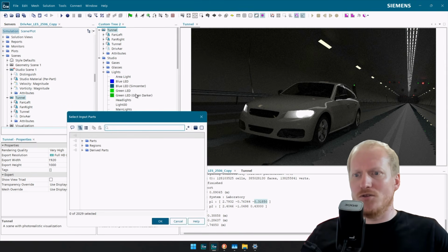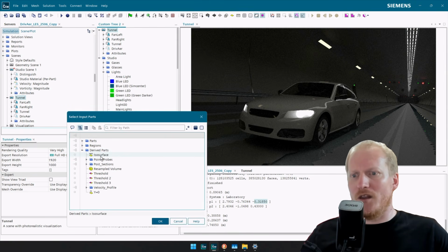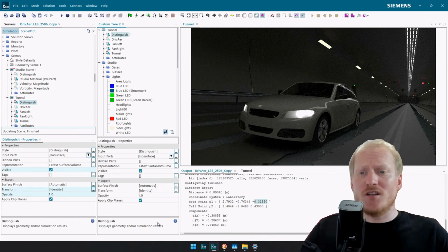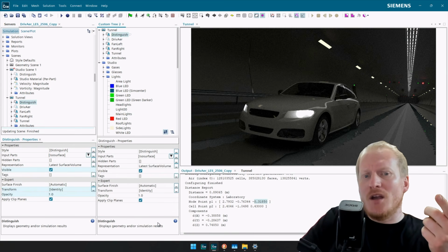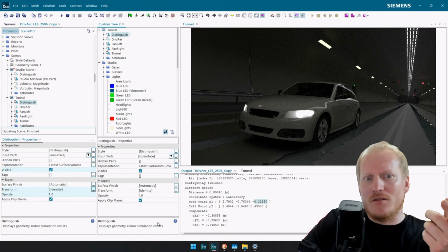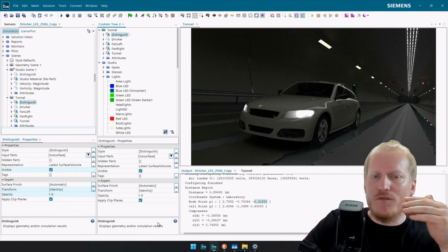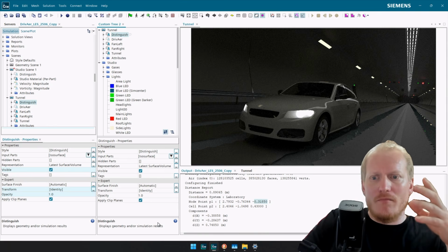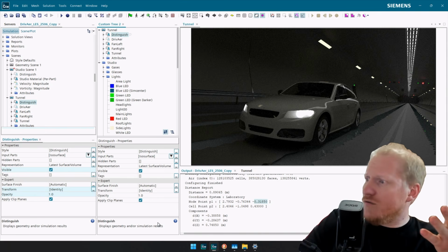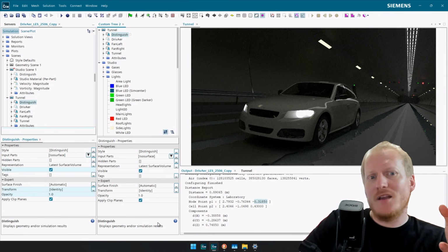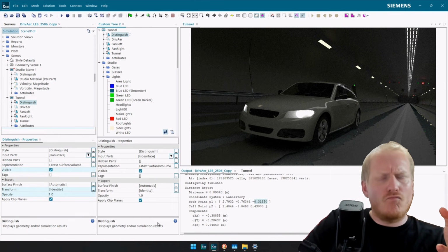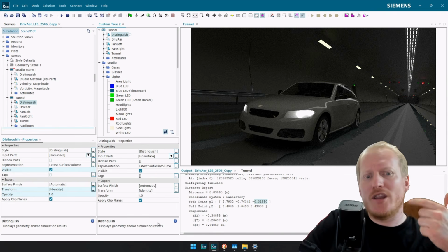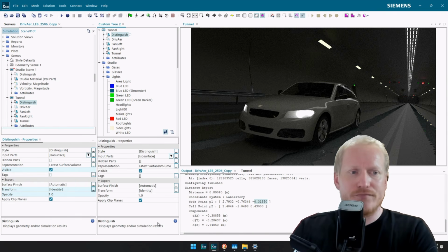We said we are doing a new displayer, and then I went for the isosurface. The isosurface is actually Q criterion, so a measure of constant turbulence, if you want. I've created that isosurface, and normally I apply to that isosurface the scalar velocity magnitude.